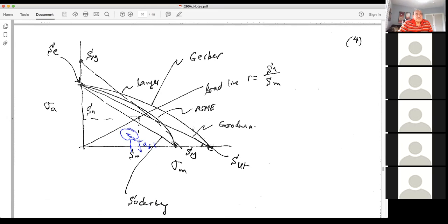There's another relationship that is more forgiving, and that is another linear relationship that we can see here, where the mean stress is assumed to even go beyond yield. So you accept some hardening.